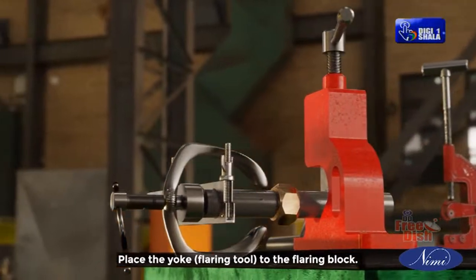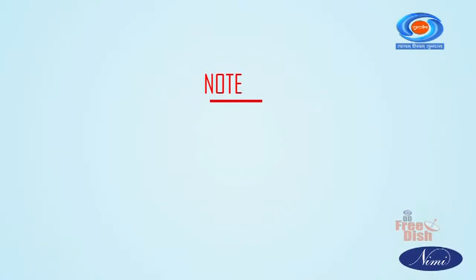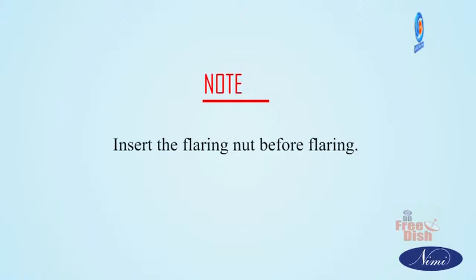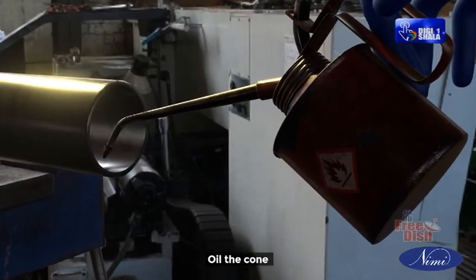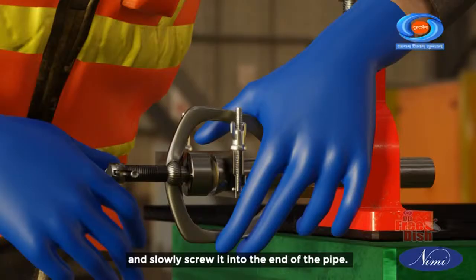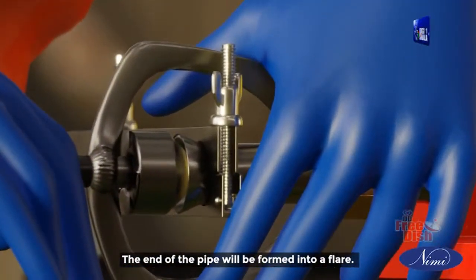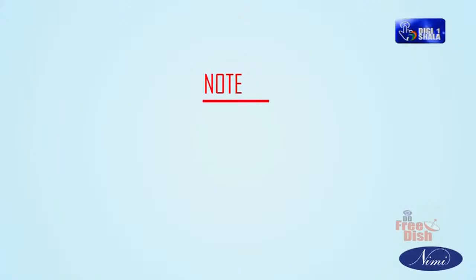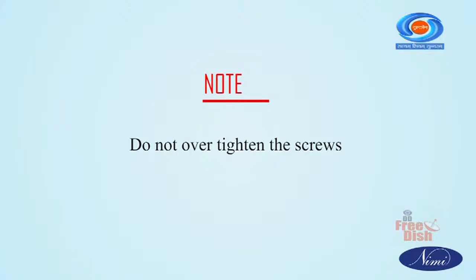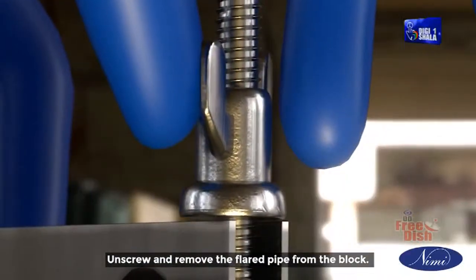Place the yoke, flaring tool, onto the flaring block. Note: insert the flaring nut before flaring. Oil the cone and slowly screw it into the end of the pipe. The end of the pipe will be formed into a flare. Note: do not over-tighten the screws. Unscrew and remove the flared pipe from the block.